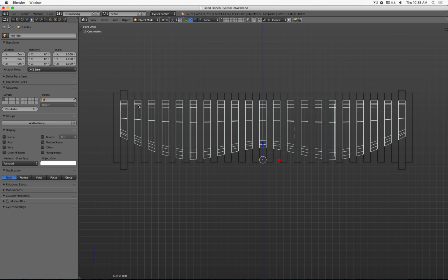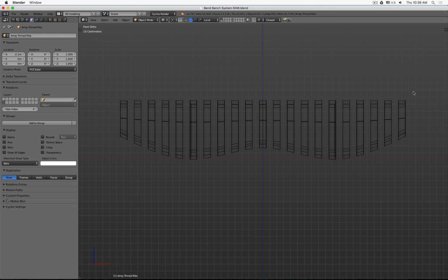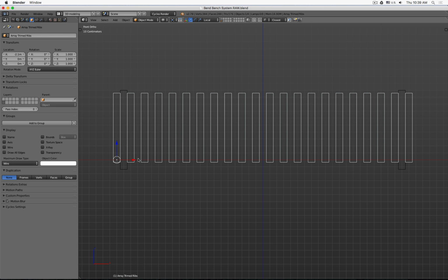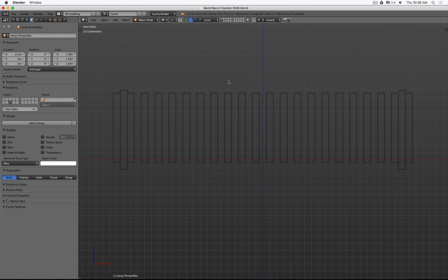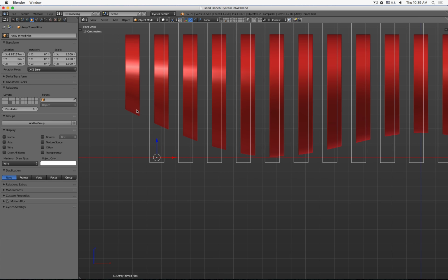So we used the solid command difference or cut. Now in this new object, instead of cutting, so removing, we actually want to only maintain what's inside these boxes. But I said that actually I only want the ribs which are inside these empty spaces and not on the outside. So I have to adjust the array for this object. So I'll move this onto a different layer so they don't overlap. Let's say there. And I can use this object for snapping.